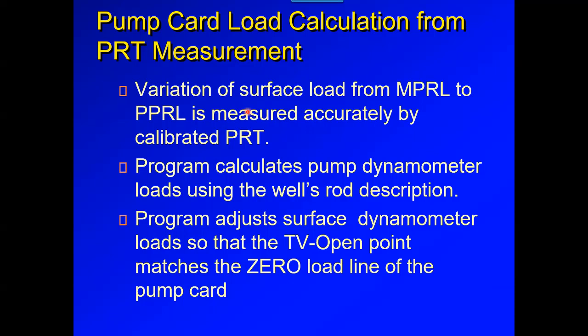So, with that being said, Echometer is a great tool, but you ultimately have to have good information inside the software in order to generate good results. Okay. Gustavo is going to talk more about what examples look like of incorrect rod description and how it can affect your dynamometer readings and calculating that downhole card. But it really is a garbage in, garbage out mentality. You have to have good information in the software to generate those good downhole cards.